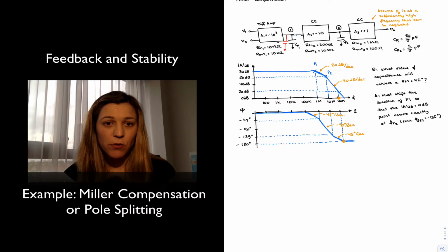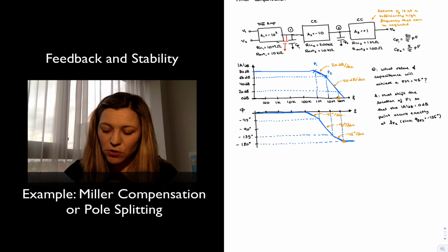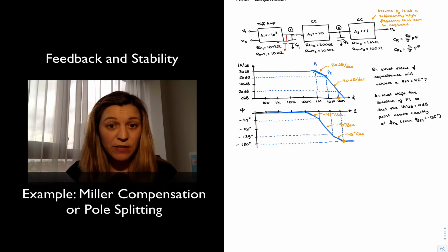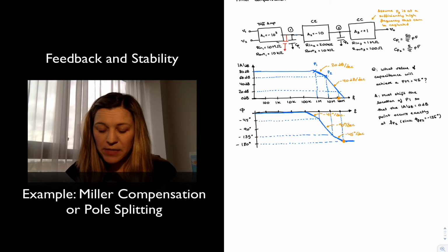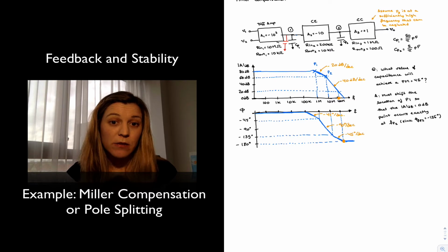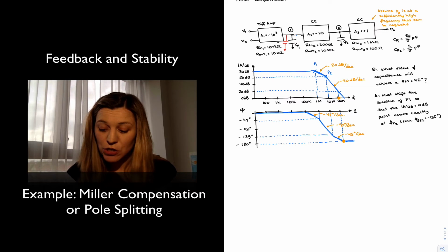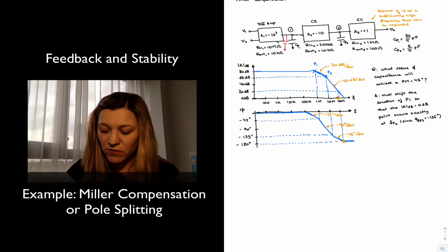Whereas if you remember, when we studied the Miller effect, we said that in essence, a capacitor connected in the feedback path of a gain amplifier was equivalent to connecting a capacitance at the input, which was equal to 1 minus the gain times the feedback capacitor, or approximately the gain times the feedback capacitor. So a capacitor that is, in this case, 10 times larger can be seen at the input if I connect a capacitor in the feedback path.